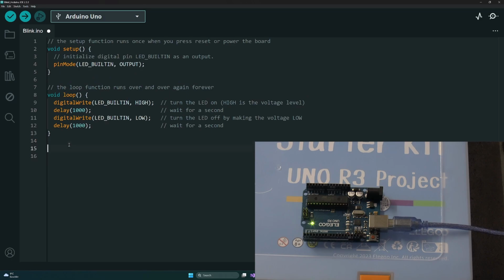Now, if you're familiar with C or C++ or any programming language, you might know the concept of a main function. A main function is basically the initial function that always runs. Arduino does not allow you to gain access to their main function. The main function is actually defined in the code of the Arduino. And just to simplify stuff a bit, the main function works something like this. This is kind of how the main function of the Arduino works.